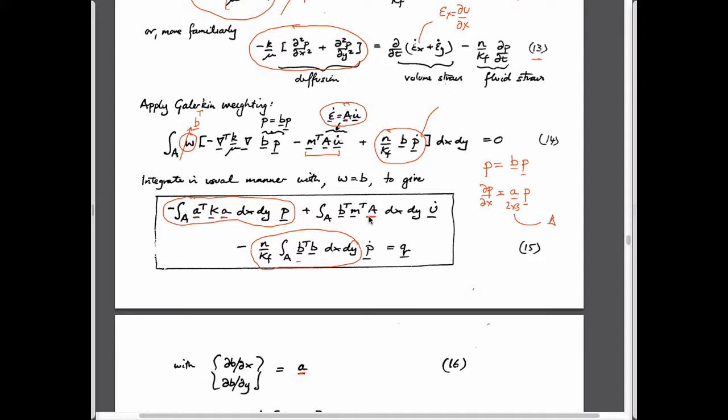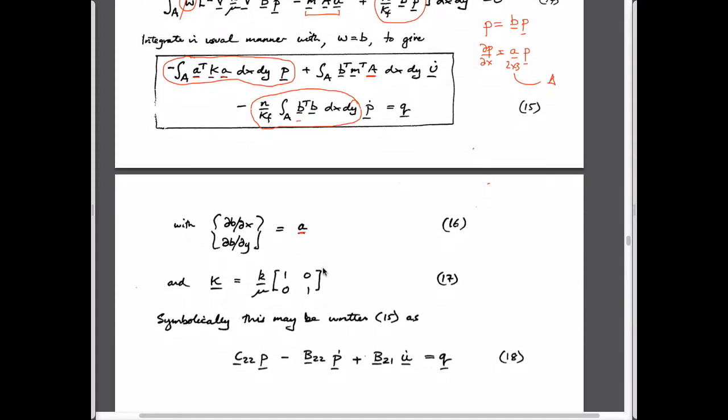This is this uppercase matrix here. And so if we know what these individual terms are, this is just going to be our Darcy's law. Fluid pressure, gradient of pressure matrix in this case, shape functions, and the strain displacement matrix in this case.